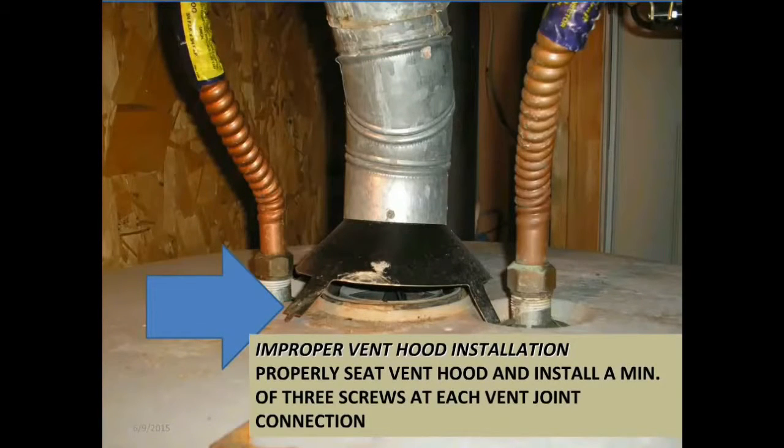Improper vent hood installation. Properly seat vent hood and install a minimum of 3 screws at each vent joint connection. Refer to the Uniform Mechanical Code 507.0, air for combustion and ventilation.